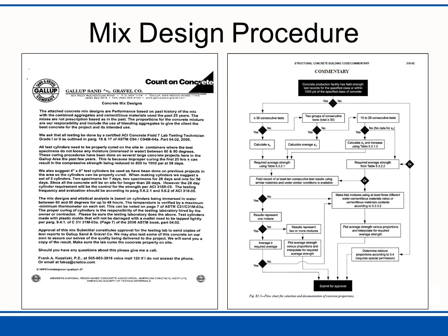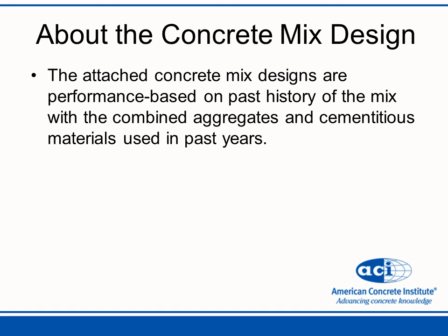The first sheets tell a little bit about the mix design on the left, and then on the right is a copy of a page out of 318 on the step-by-step procedure to have the mix design submittal be approved by the engineer. And the information about the mix design, we should say in there that the mix designs are performance-based.